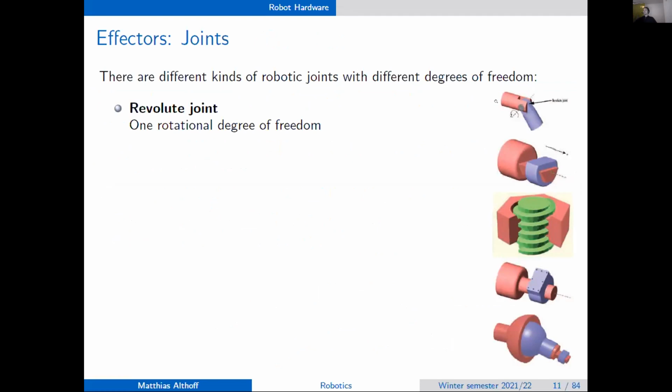So what it means, let's say you have 2 objects, each of them has 6 degrees of freedom in 3D space. And then this joint fixes 5 degrees of freedom and leaves 1 free. So the first object has 6 degrees of freedom plus 1 more degree of freedom, so these two objects together would have 7 degrees of freedom. And if you fix the first object, you glue it to something, then all 6 degrees of freedom are fixed, and you have only 1 degree of freedom, which is the rotation of the second object.